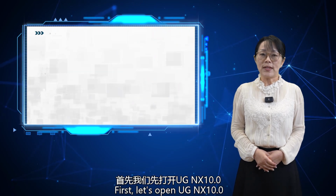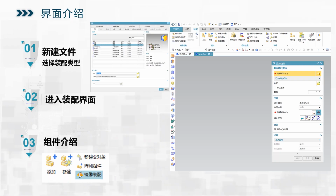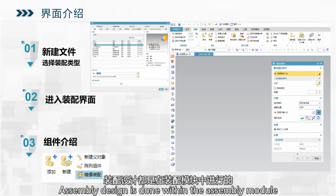First, let's open UGNX10 and create a new assembly file. In the Template tab, we select Assembly, name it Assembly, and click Confirm to enter the assembly work environment. Assembly design is done within the assembly module.